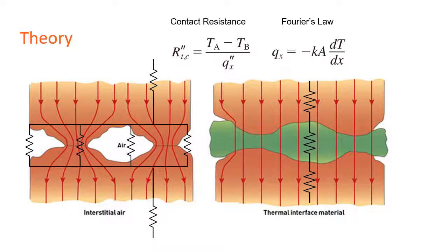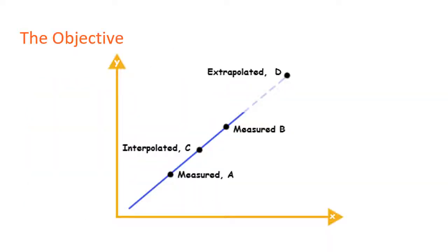When two solid surfaces are in contact, although they may appear to be touching, there are microscopic spaces where they do not touch. Heat must be transferred through the small amount of surface in contact and through these pockets of air or other interfacial fluid. There exist many different methods of dealing with this, including mating the surfaces at high pressure, smoothing out the surfaces, or using some interfacial fluid with a higher thermal conductivity than air.